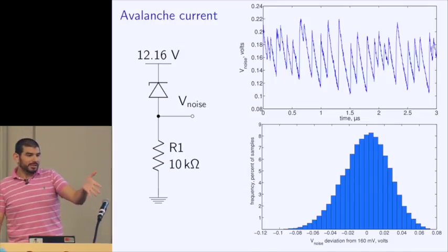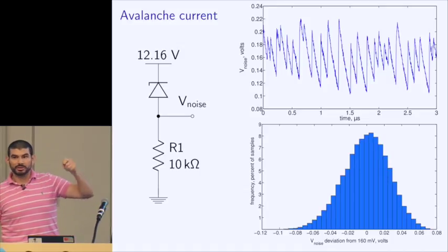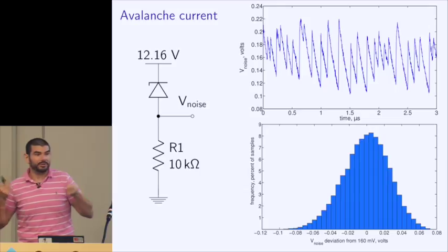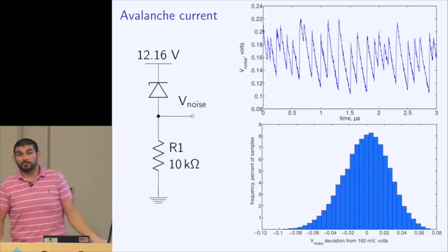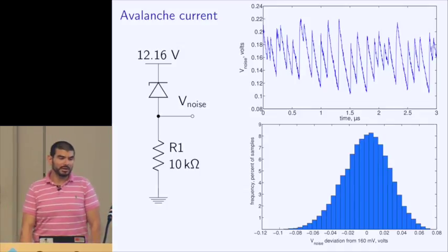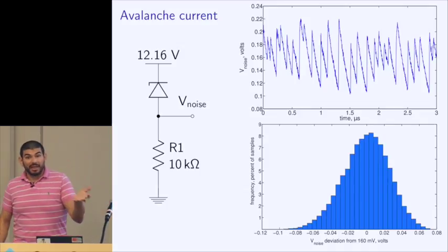Not quite. Here we had to adjust this voltage to just right to get the thing to work. And if I had taken a different diode and stuck it in there instead, that wouldn't have worked quite the same. So if I wanted to build 1,000 of these devices, maybe 200 of them would fail. So how do we get around that manufacturing tolerance?